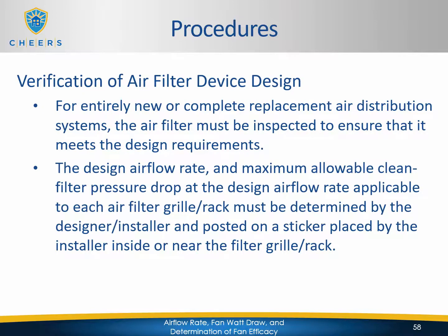Verification of air filter device design. For all entirely new or complete replacement air distribution systems, the air filter must be inspected to ensure that it meets the design requirements. The design airflow rate and maximum allowable clean filter pressure drop at the design airflow rate applicable to each air filter grill or rack must be determined by the designer or installer and posted on a sticker placed by the installer inside or near the filter grill or rack.